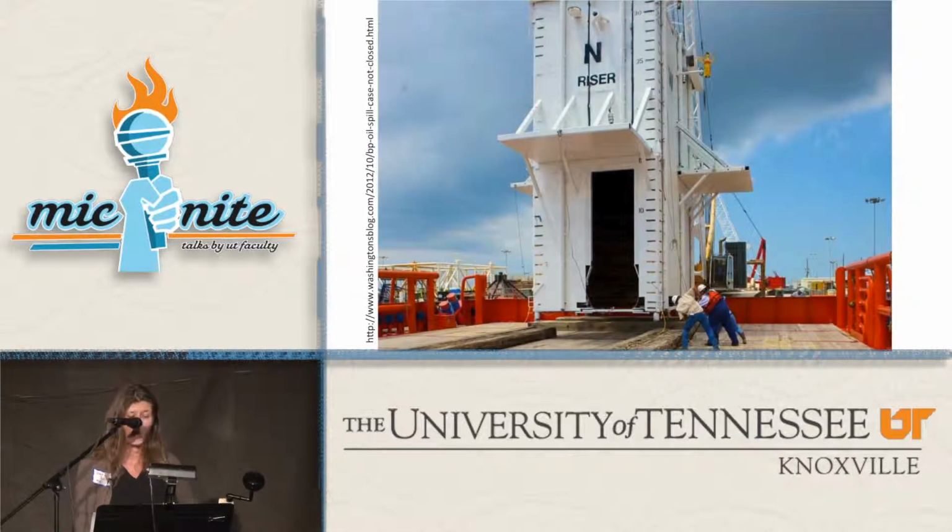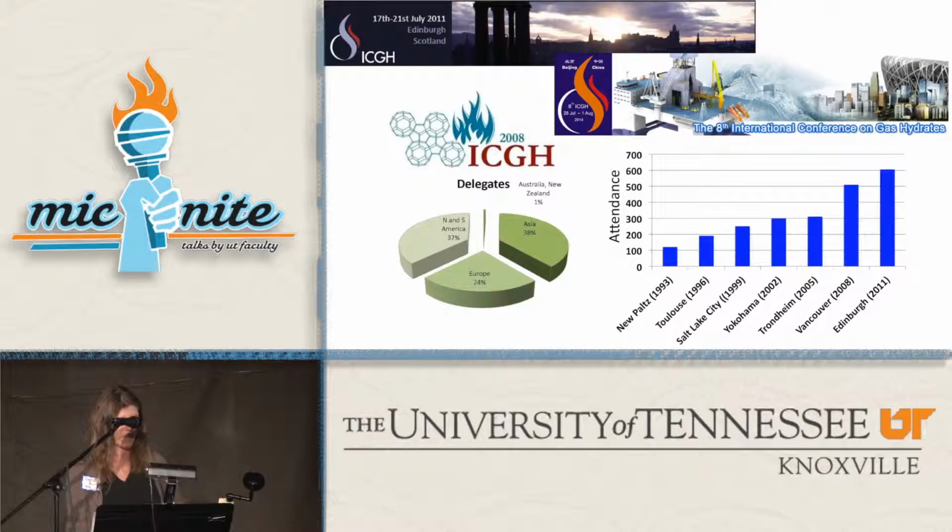Remember the Deepwater Horizon oil spill? One idea was to cover the largest leak with a 280,000-pound containment dome and to pipe the oil into a storage vessel. It failed due to methane hydrates forming and plugging the top opening of the dome. The containment dome also became buoyant since the density of methane hydrate is less than seawater and floats.